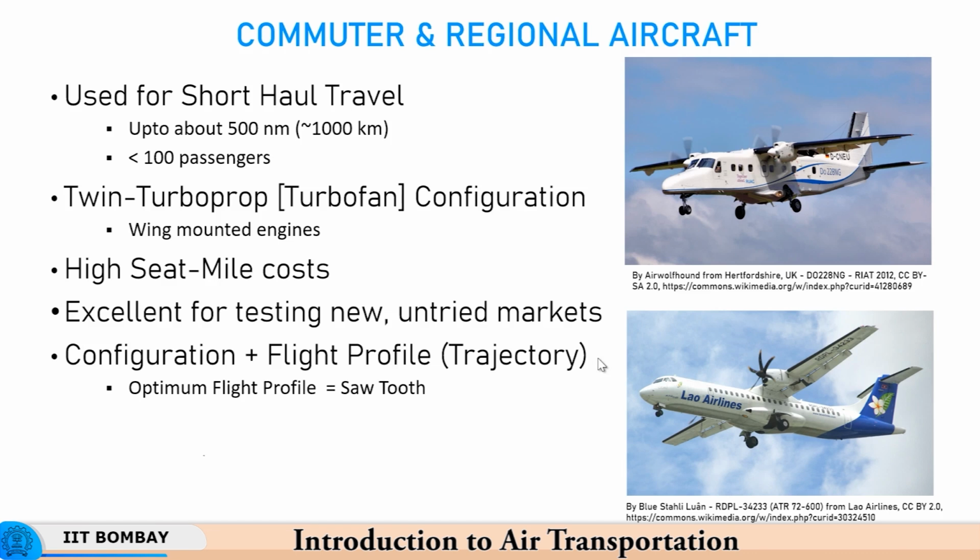So, if you want to maintain the speed, not compromising on the speed, then you have to have flight at a lower density than in the previous case, and that means it is better for you to climb up. So, the cruising altitude can change from 35,000 to 38,000 to 41,000 during the 10, 12, 15 hour flight of a long range aircraft.